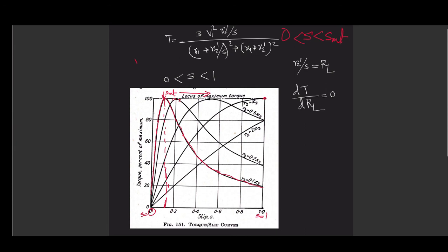And that is also logical, because what does maximum torque mean? That is maximum PG by omega s. So it is something that relates to the maximum value of how much input you can absorb for a machine. So this maximum value obviously should be governed by the input side data, not something that is dependent on your output side.